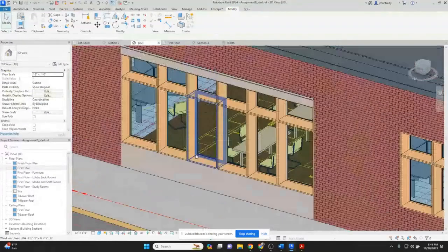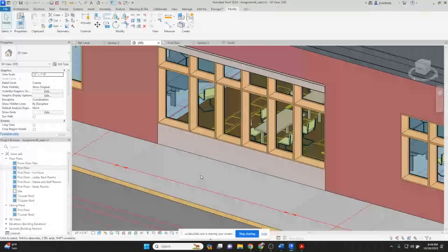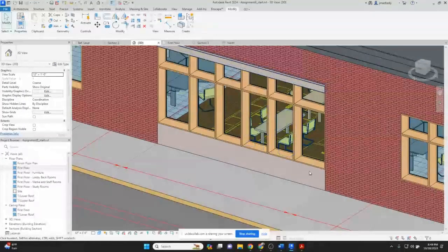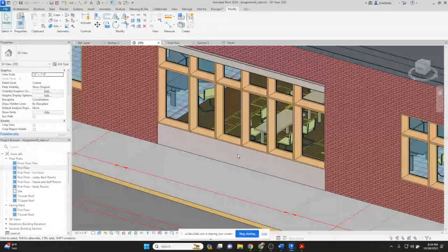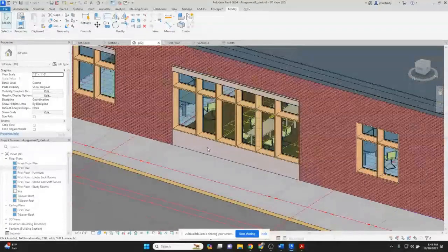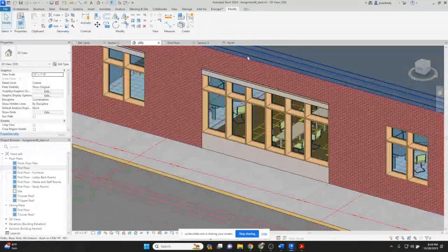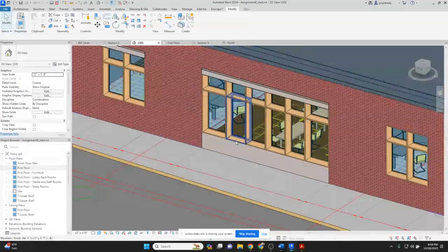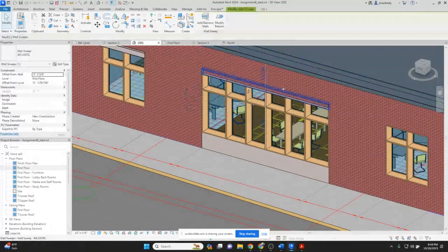So I painted that. This section was still going to show brick down there, but this is a very quick way of changing materials on a surface where the cross section is not important to me to display correctly. Otherwise, I would build this as a detail and add it to the wall in a similar fashion that I added that lintel.